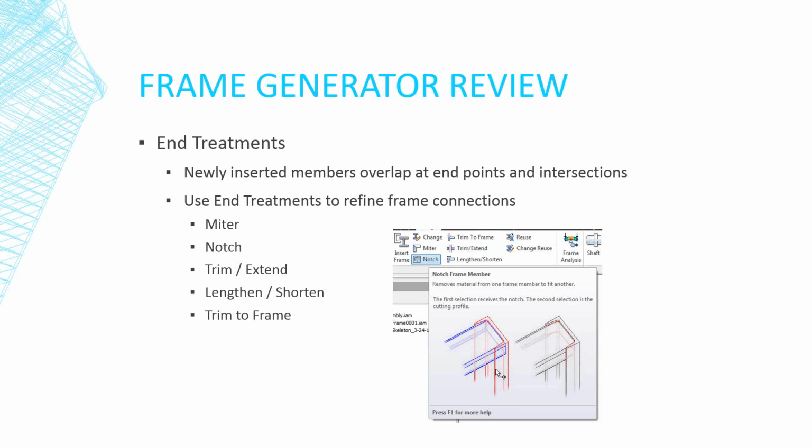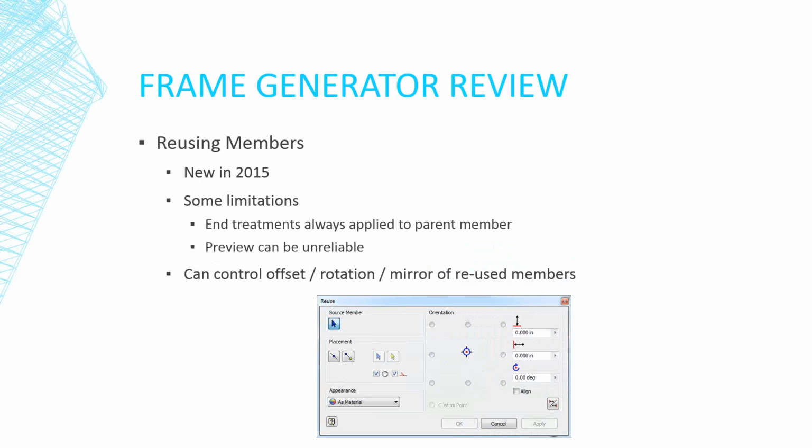It saves a little bit of money if you've got guys that can quickly drill and tap everything. So in that case, we would just order a bunch of straight sections to length, not do any fancy miters or anything. So we just have a cut list. If you do your miters right, the cut list just falls out as a result of doing all your miters.